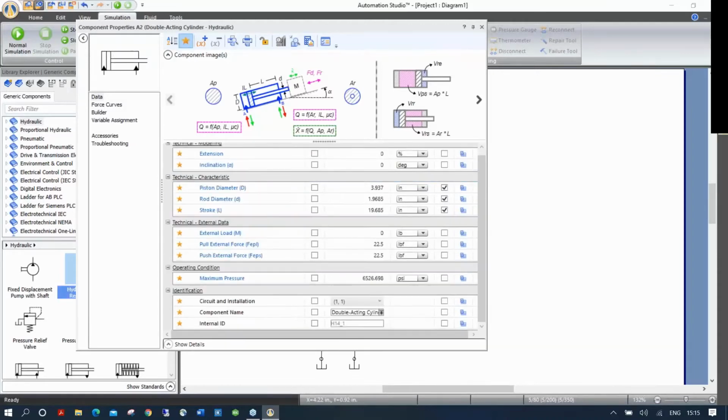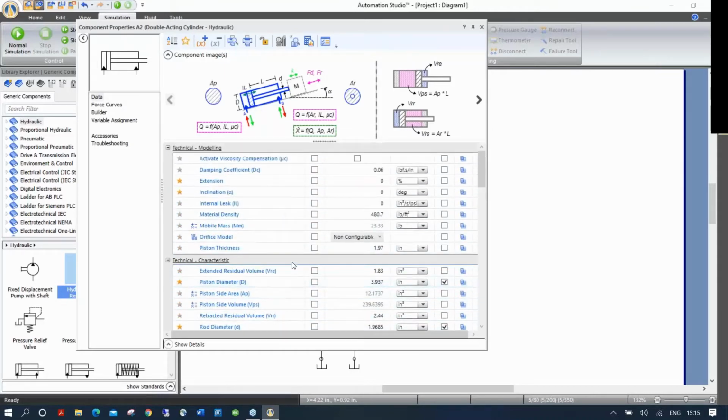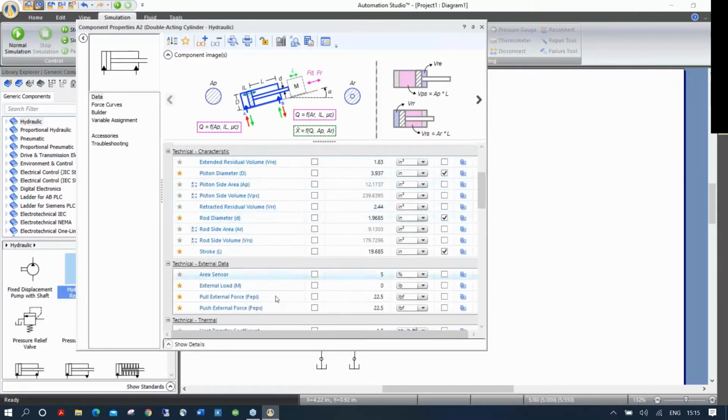I've had people calling me saying, I cannot change a specific unit for a component, and it's because the field was hidden by default because it wasn't a favorite one. So by simply unchecking this, you will display a lot more possibilities, okay? So let's put right now an inclination of 40 degrees for that cylinder. And I'm going to put an external load of, let's say, 5,000 pounds.